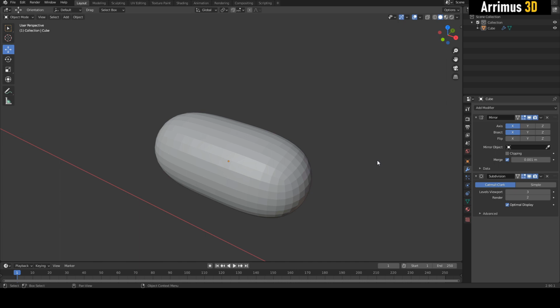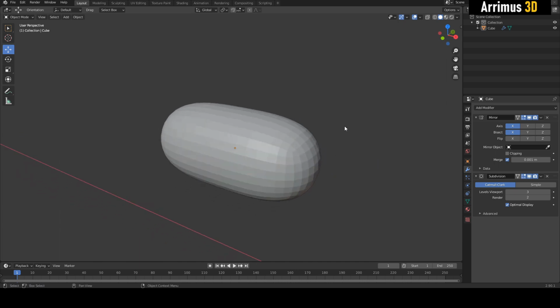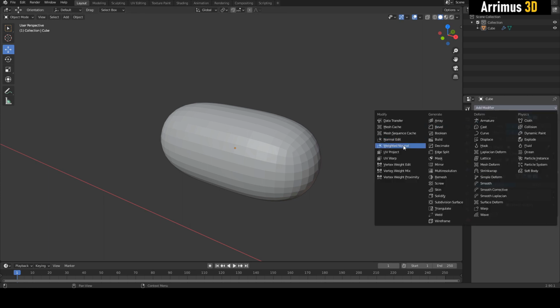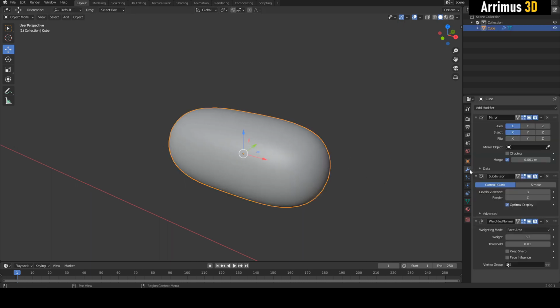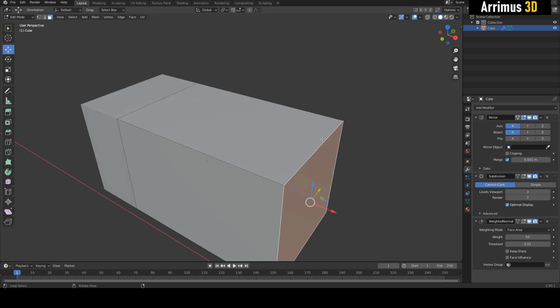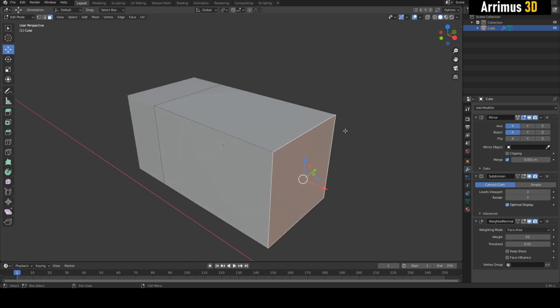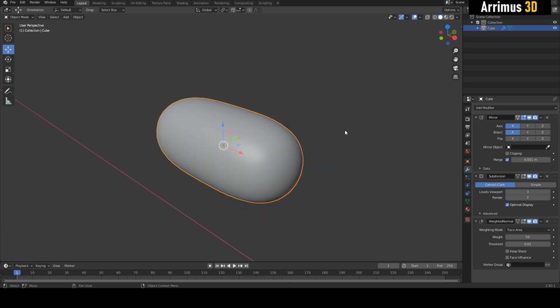And let's use a lesson from my previous video on Blender Quick Tips to have a more interesting, better viewport behavior. So we're going to apply with normal, and we're also going to go in here and enable normals auto smooth. And also we're going to turn off this subdivision with normal in the viewport. This way I could pretty much model like this, then press tab to find a result.